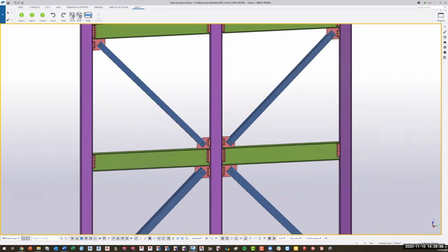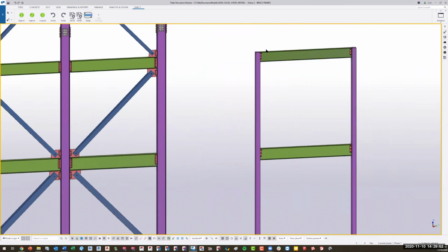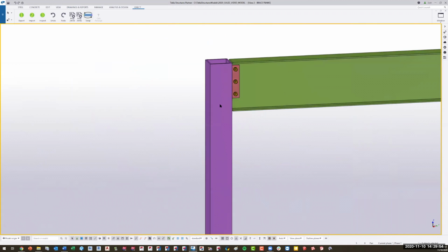Okay, so when you get into a punching shear situation, the solution usually is to weld a plate onto the face of the HSS column that solves the punching shear problem. Okay. So currently, that is not something that we have in our connection library. Now, like I said before, we haven't really run into that too often in that scenario. Most of our clients just say, you know what, it's acceptable to just use 15th edition, and pretty much in all the jobs we've done that with, it has worked out.